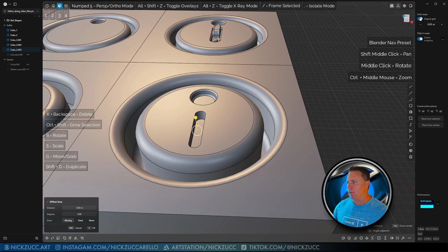So again, I'll tap 2, and you can see I've got all these different parts and pieces of this curve. I could hold down Shift and I can keep going around this. That's a lot of work. If I go to 2 and I click on this edge, if I hold down Alt, I can do the entire loop like this. And if I do Alt and hold down Shift, I can keep adding to that selection on here. So now I'm going to do a chamfer on here, and I'll do something that's a pretty decent size like that right there.